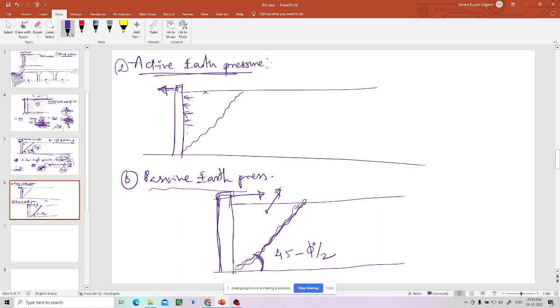So the wall cannot move on its own. Here you can understand at least there is a soil, it is pushing. Because of that push, it is moving in this direction. We are allowing some movement, but we can't allow it totally because soil will fail. So we will allow the movement just before its failure. Till then it can move. After that it should stop. So according to that, this wall is designed. But what about this? How is this wall moving in this direction?